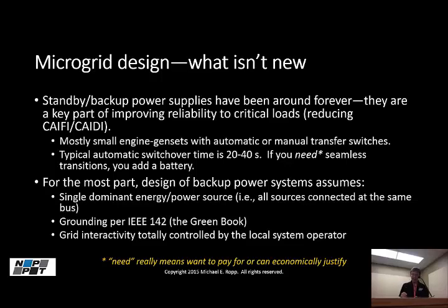I was just going to say that you have to be a little careful. A lot of people assume that if I black out the system and then restart, that simplifies the design. Yes and no, because does it mean I don't have to handle the seamless transition? Yes, but now I've got a black start. So there are considerations both ways. And I mentioned this here, that for the most part, backup power systems assume that I've got a single source bus that's going to dominate the microgrid.